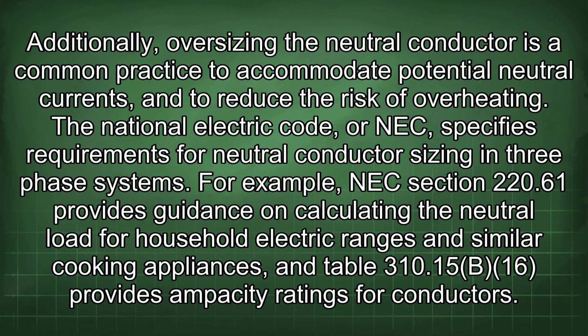The National Electrical Code, or NEC, specifies requirements for neutral conductor sizing in three-phase systems. For example, NEC Section 220.61 provides guidance on calculating the neutral load for household electric ranges and similar cooking appliances, and Table 310.15(B)(16) provides ampacity ratings for conductors.